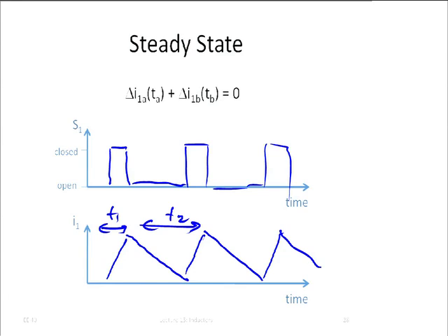No, it will go down like this if the voltage across the inductor is constant, right? Which is an assumption that we still have to make sure is true. Then the current goes linearly down. This is precisely the reason why I chose this as something to explain what inductors are doing, because there isn't a lot of complicated math here. There are not even any exponentials. But it's doing something really interesting, something that you take for granted, but you're electrical engineers, so maybe it's a good idea to have an idea what's going on inside. All right.